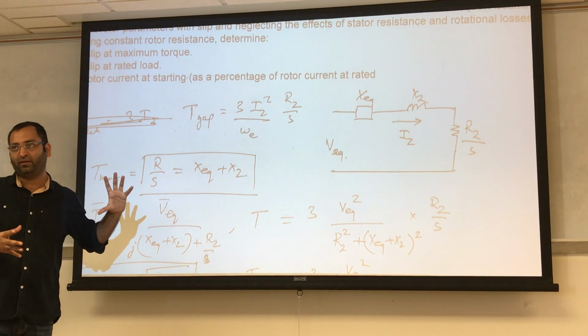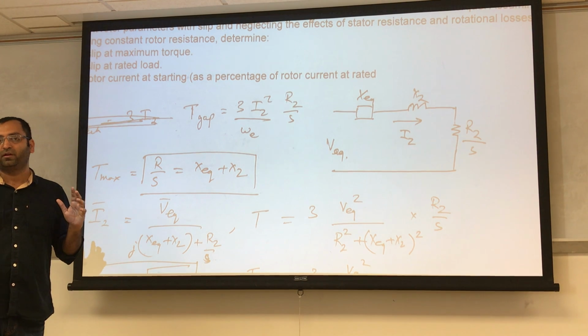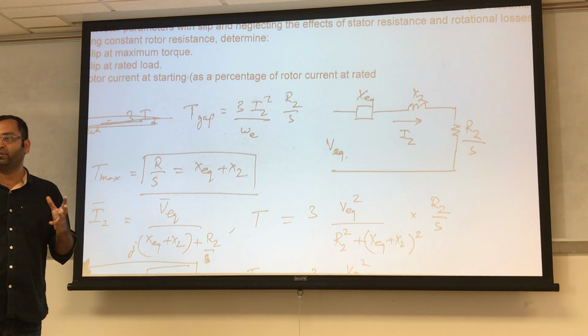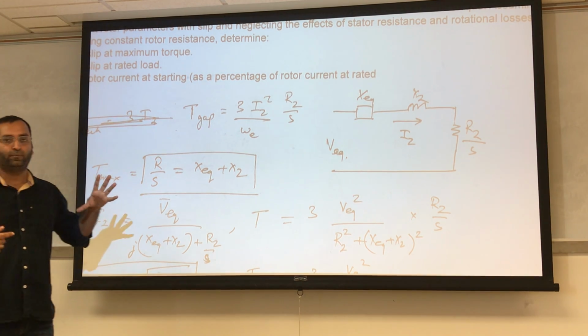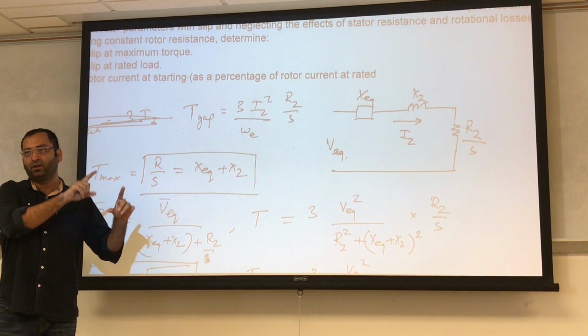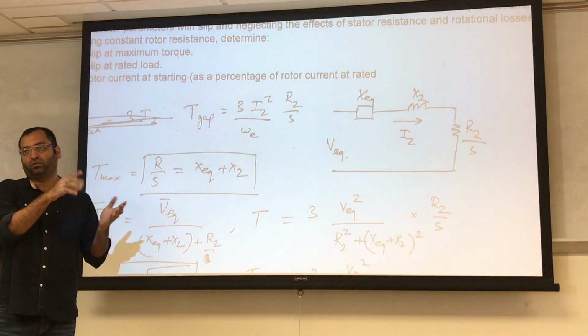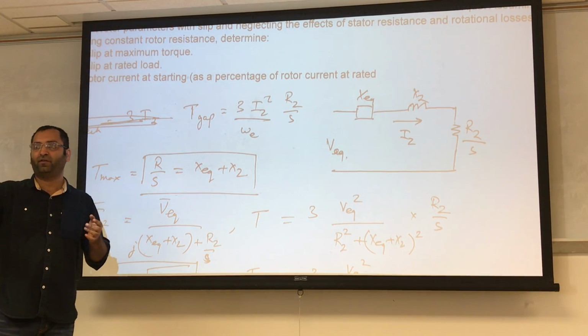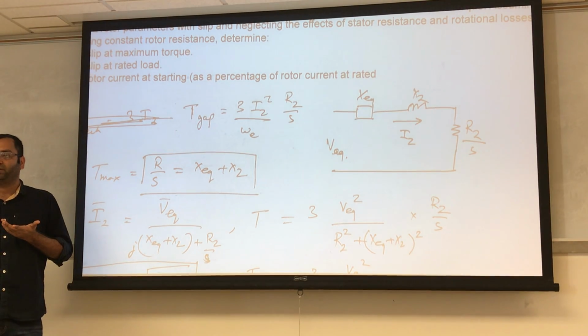If I am giving a voltage input to a motor, what's the resultant we are expecting? The motor is rotating. So how much power is the motor giving when it's rotating? And the input power is when you are giving the input as voltage, so V I conjugate will be the input power. So to find the efficiency, you can just divide the shaft power over the input. Is it clear?